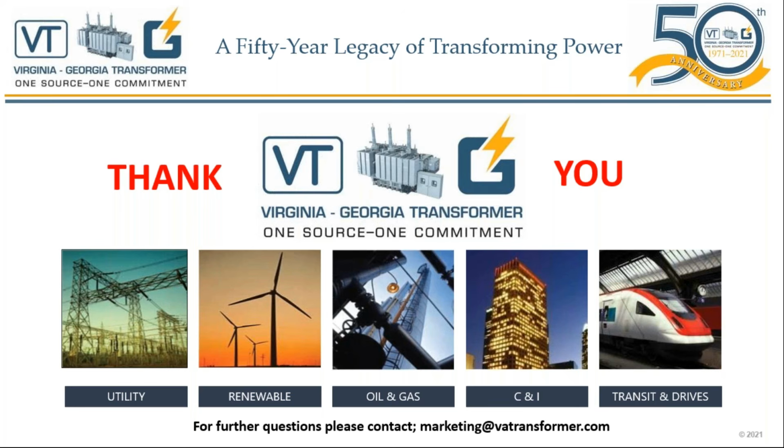If the DGA is showing PD activity, then it is recommended to test that. But DGA is very commonly used in the industry as a routine, for any transformer from small rating to the biggest rating. And PD is not very common. I think most applicability of that is 230 to 345 kV and above.